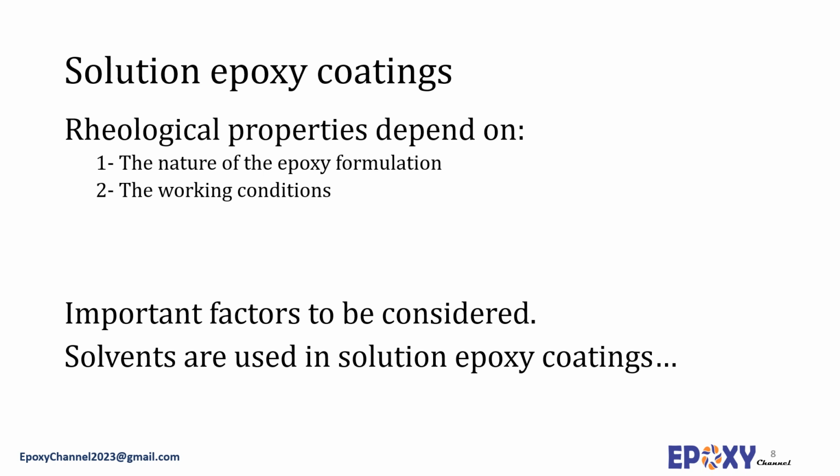In addition to the epoxy coating formulation and the proper solvent set, for a successful coating application, other factors such as the condition of the surface prior to coating, concentration of the solution, curing technique, pot life of the solution, etc. have to be considered. The presence of pigments and fillers also affects the rheological properties of the coating, as after the addition of these additives, the coating may be either Bingham bodies with a yield stress, pseudoplastics, or thixotropic.